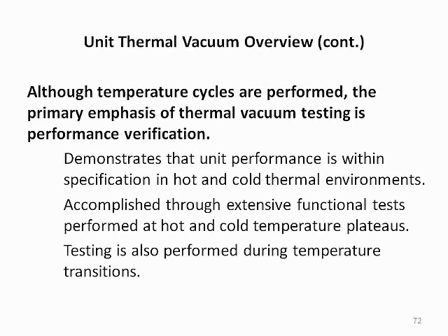While temperature cycles are performed in thermal vacuum tests, the primary emphasis is performance verification. The thermal vacuum test demonstrates that unit performance is within specification in hot and cold thermal environments and is accomplished through extensive functional tests performed at hot and cold temperature plateaus. Functional testing is also sometimes performed during temperature transitions.